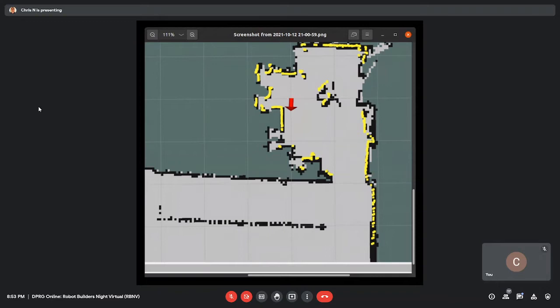You just turn it on and you set things up so it gets the data, and it spits out some data. In this case, it spits out a map, and it spits out a new pose for the robot. That's what it believes the correct pose to be, right? Again, now grid mapping is interesting because it takes into account odometry, right? So it uses odometry to help with the alignment of the laser scan against the map, right? So that it doesn't completely lose track of things and supposedly use less processing power, but I haven't necessarily seen that.